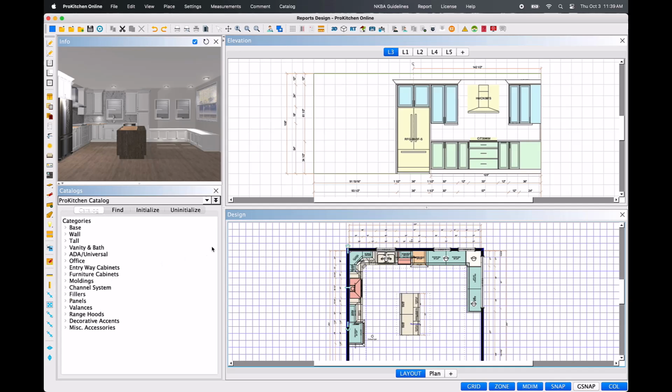Left-click once to grab. Move the mouse into the view panel, and left-click on the first point. This time, drag the mouse vertically and secure the dimension line at the next desired point with a left click. Again, use the right-click toolbox option of Move to relocate the dimension line if desired.